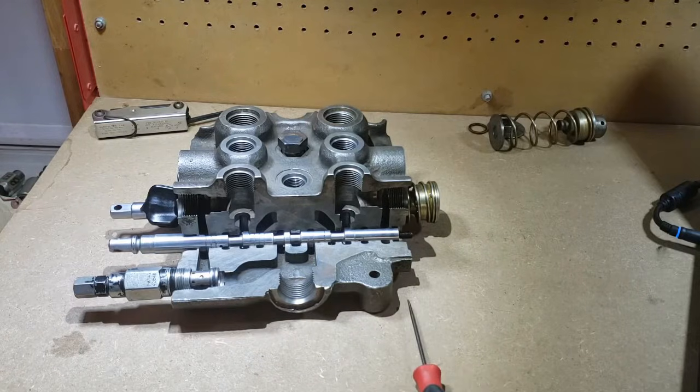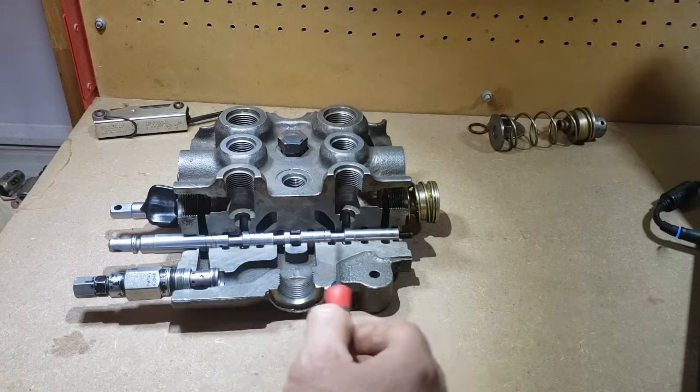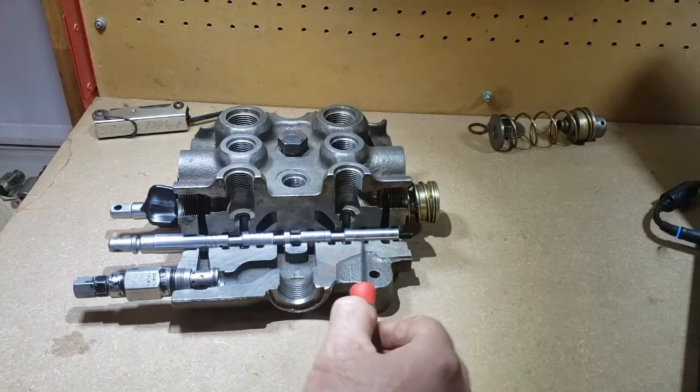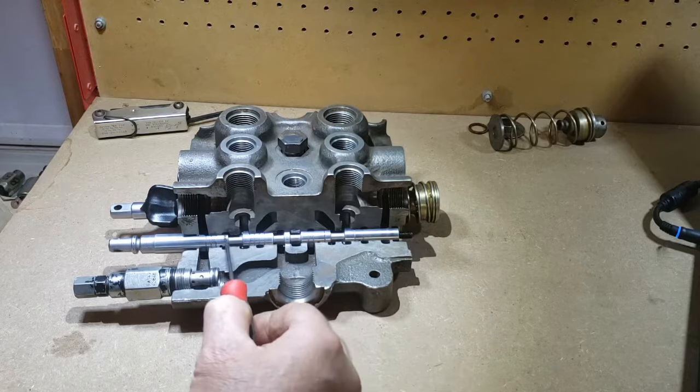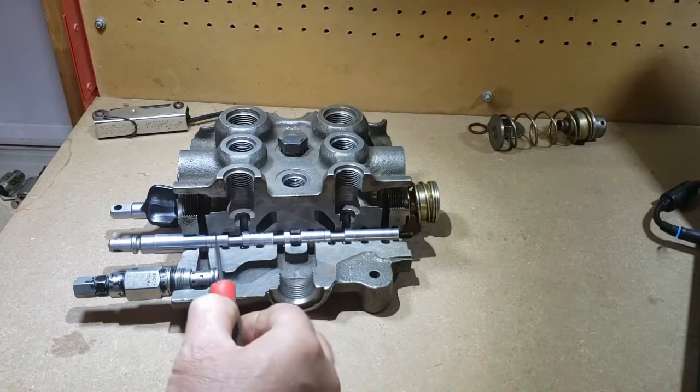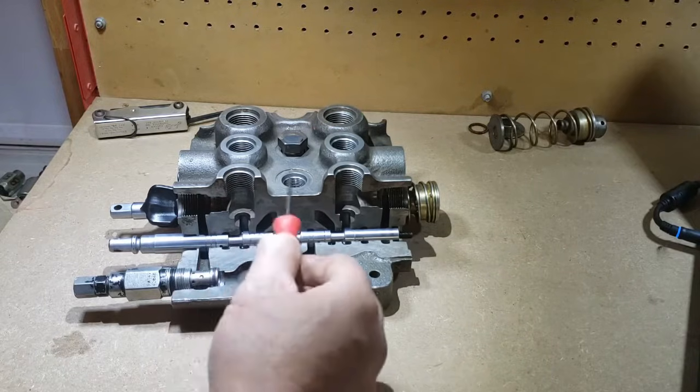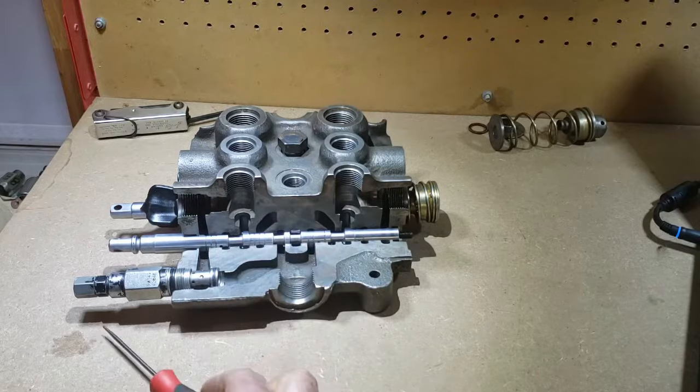If it was a parallel flow valve, then it would be a little simpler in here. Instead of dumping oil back into these extra sort of return passages, oil returning from an implement would just go right into drain. But we're sort of going to regenerate that oil back into the open center path.